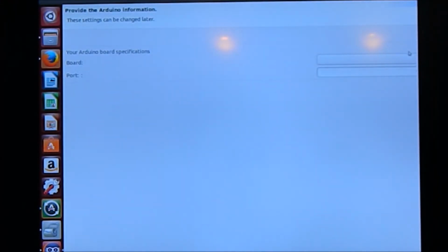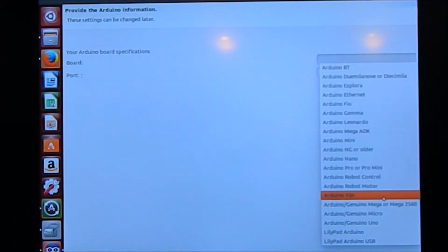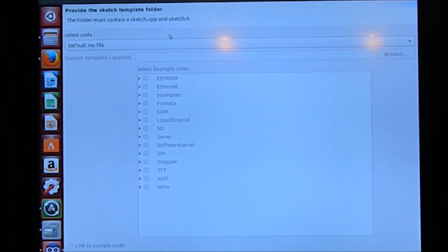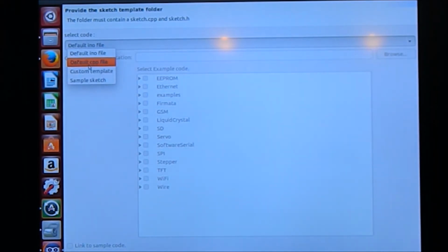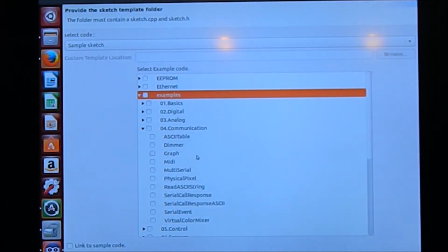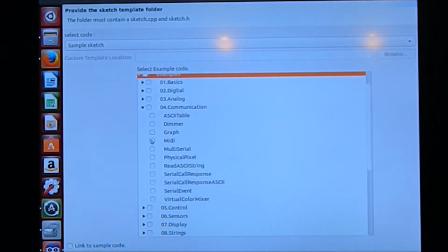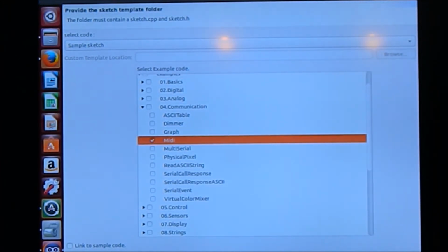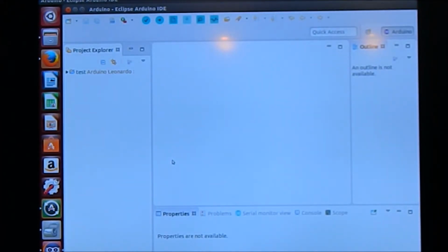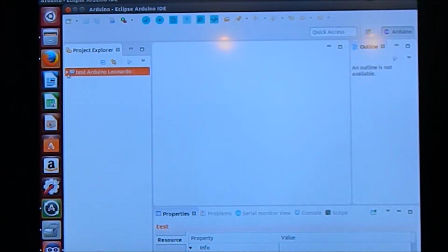Arduino Eclipse plugin. And here you see that there's no boards.txt list because there's only one. There's only Arduino AVR. I'll make another movie on how to add other boards. And we'll select a project to create just one of the examples to get going, nothing specific. The nice thing about V3 is that when you create your project, all the libraries are automatically included in your project. Everything is actually done automatically, just like in the Arduino IDE.